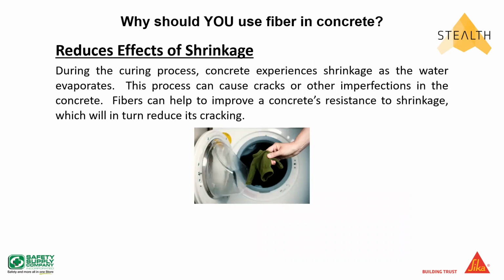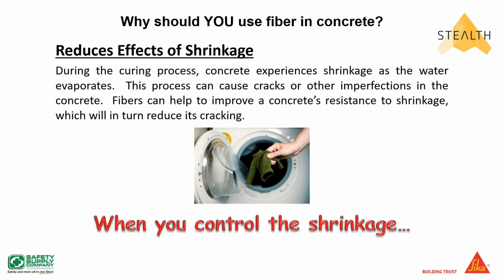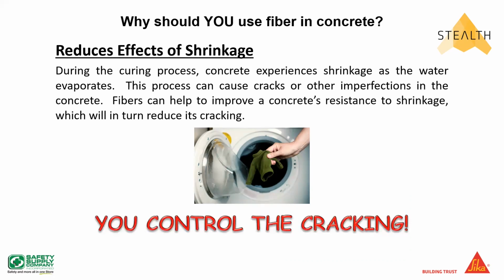This is a big one. Reduces the effects of shrinkage. Of course, it's all about the shrinkage, as it says there. During the curing process, concrete experiences shrinkage as the water evaporates. The fibers can help improve the concrete's resistance to the shrinkage and will in turn reduce its cracking. So what I like to say is, when you control the shrinkage, you control the cracking.